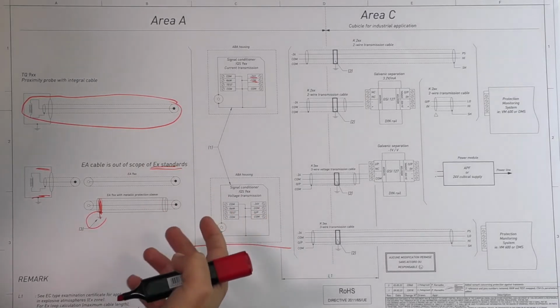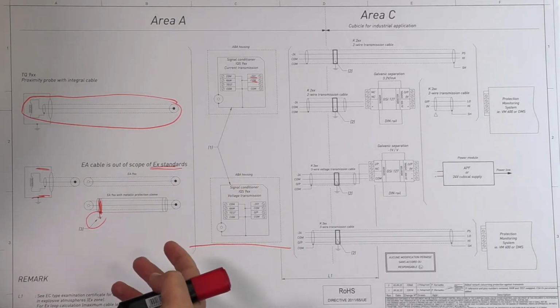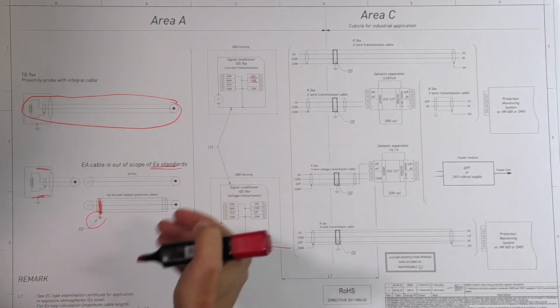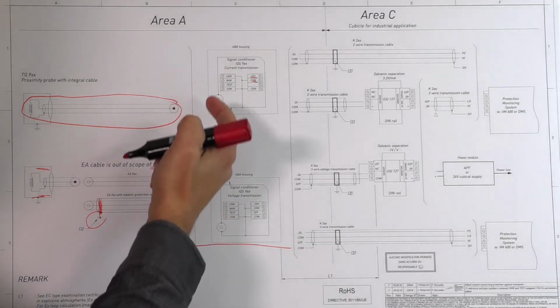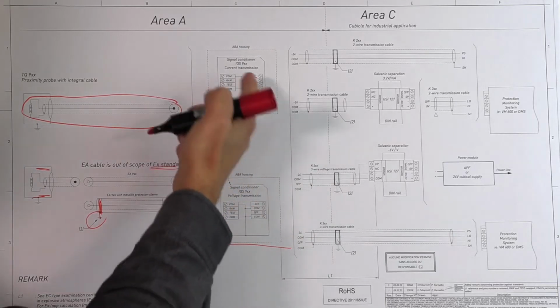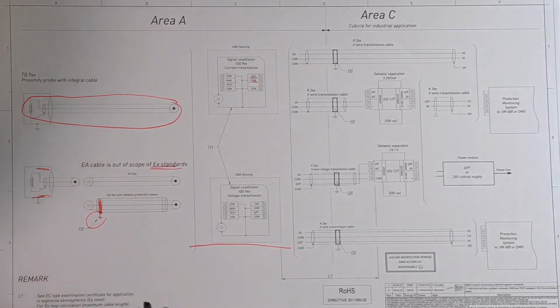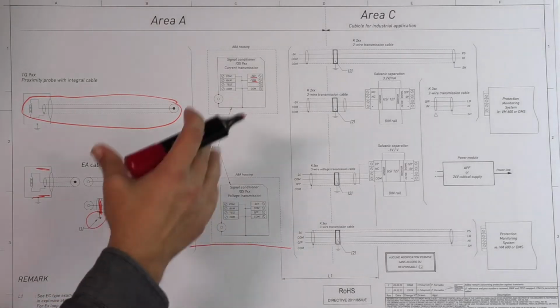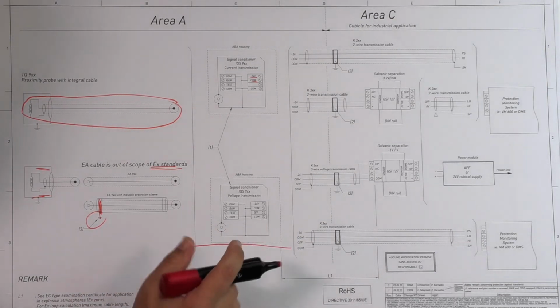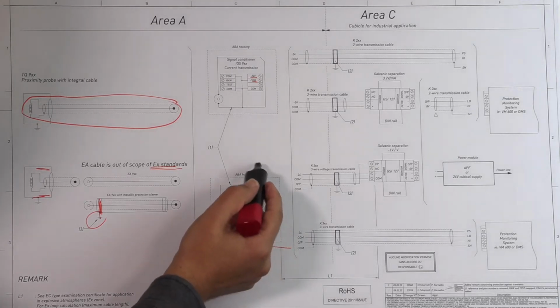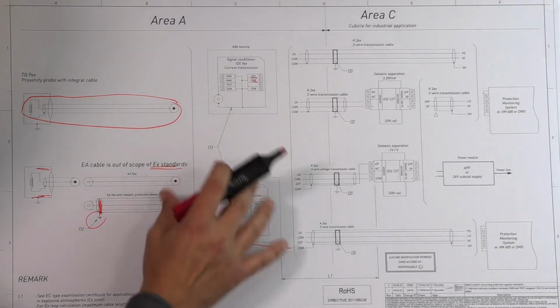There are cases when you have a 24 volts power supply, but where the negative of this power supply is connected to the ground. So if you try to connect that negative to minus 24 volts and the positive to COM to obtain the minus 24 volts, you have a short circuit that will not work. It's one of the historical reasons that's pushed most of the proximity probes to be considered floating to avoid that problem. So these units are floating locally.